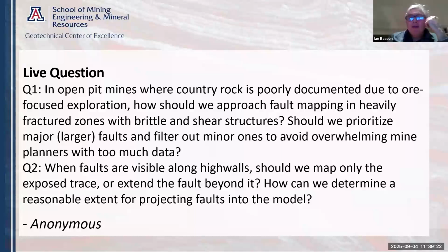Yeah, I think, and I don't want to be parochial and nasty about this, but it does depend on the development of the mining industry in that particular country. You can go to certain countries, like in the Middle East, where if you see a displacement in core, they'll call that a fault. So they think every offset equals a fault. But if you end up in Canada, they've got through that phase, and they know that that's not a fault. They know that even something on a bench scale, you could just maybe bag into being a joint with minor displacement or something like that.